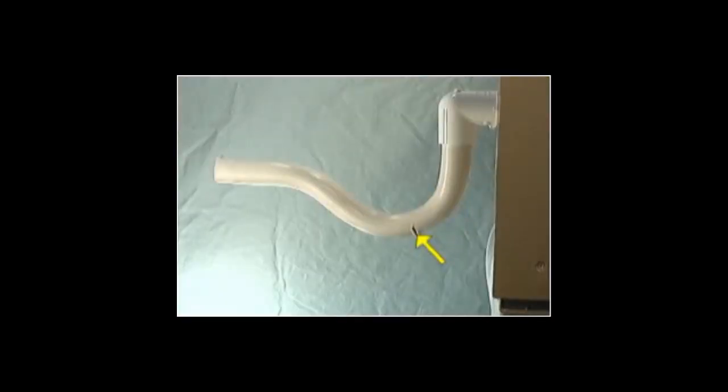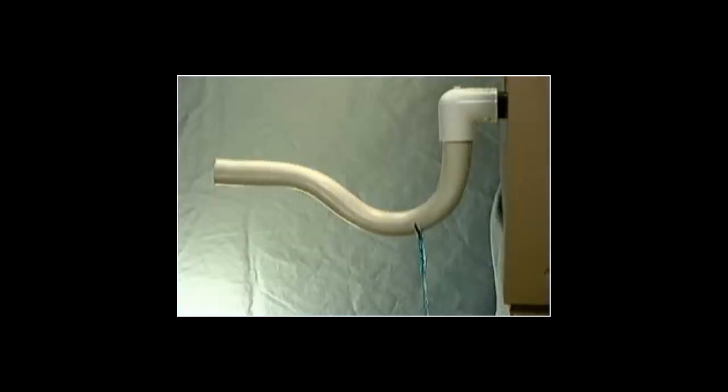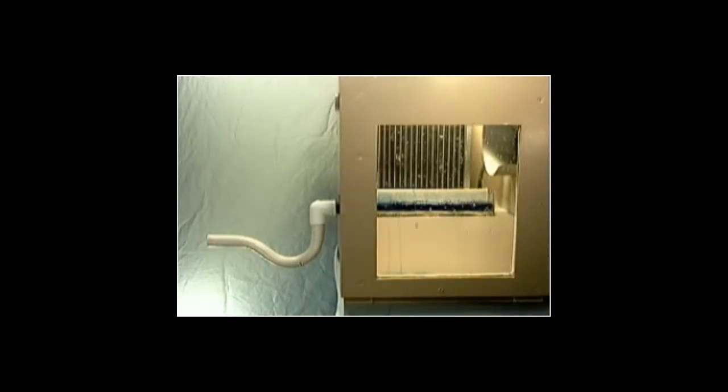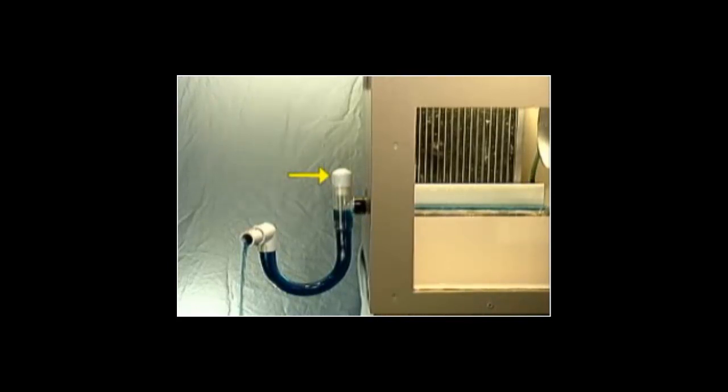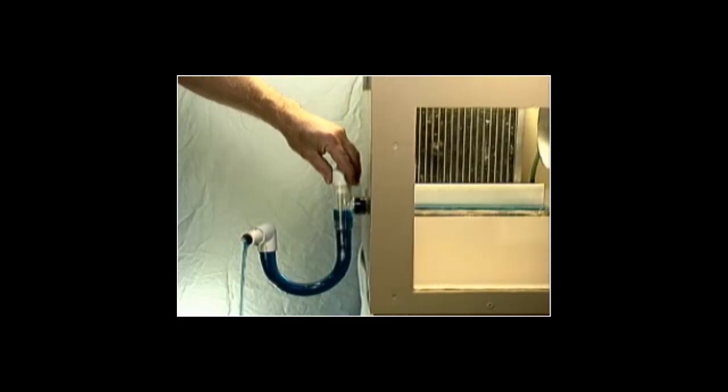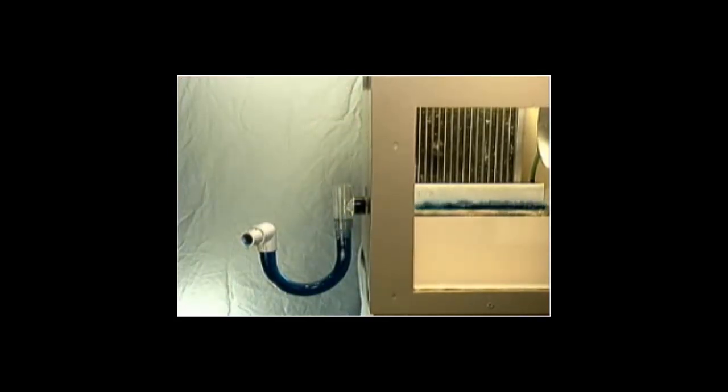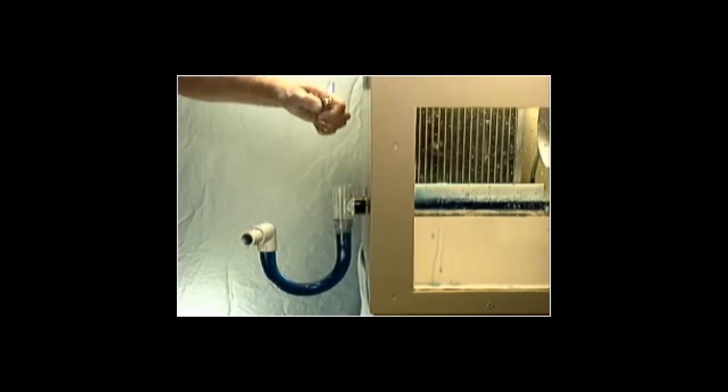Condensate traps exposed to freezing temperatures are frequently ruptured, as depicted here. Since a ruptured trap cannot retain condensate, it acts like an empty trap. Observe that water leaks from the trap and allows air ingestion and condensate blowing during the cooling operation. Ports provided for trap cleanout and priming must be covered during all operating conditions. If for maintenance conveniences the port is left uncovered by design or service personnel, the trap acts like a missing trap and causes all the same problems.